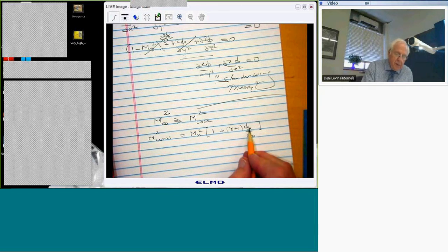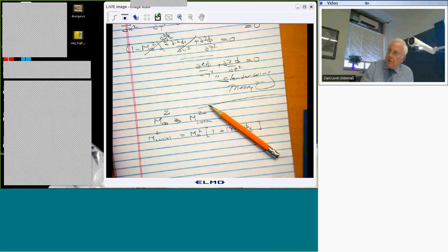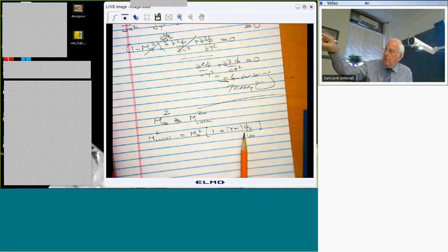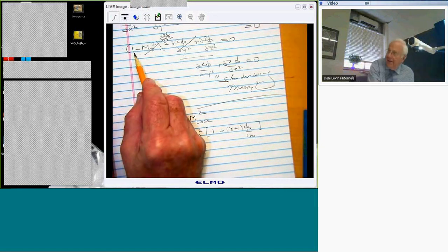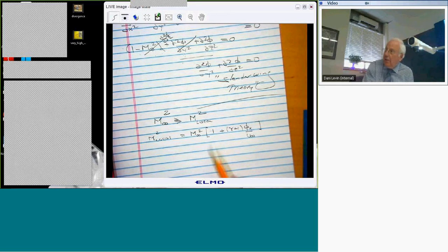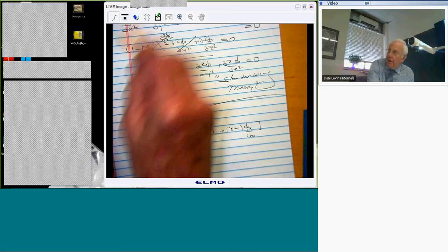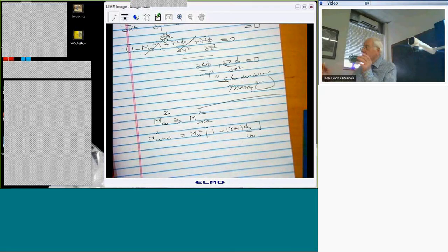What is this? Well, first of all, without that term, it's just classical theory, right? This term is the fluid velocity component in the x direction, right? Divided by the free stream. And really, this thing typically is very small compared to 1. But the reason we retain it is because when the Mach number itself is 1, there's this other 1 that's canceling this term, and therefore I'm going to get 0. So this is small compared to this. This is small compared to a lot of things, but it's not small compared to the difference, which is canceling when the Mach number is very close to 1.